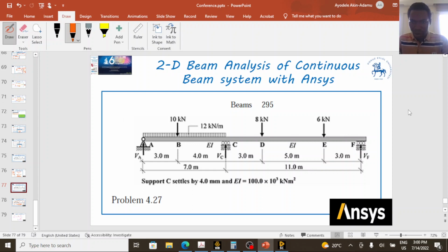Salient points on this beam problem are point A, point B because there is a point load there, point C because our uniformly distributed load ended at C or we have a reaction at that point, point D because we have a point load at this point, E because we have a point load at this point, and point F also because we have a reaction force at that point. So we have to create edges at the top and bottom at these points.